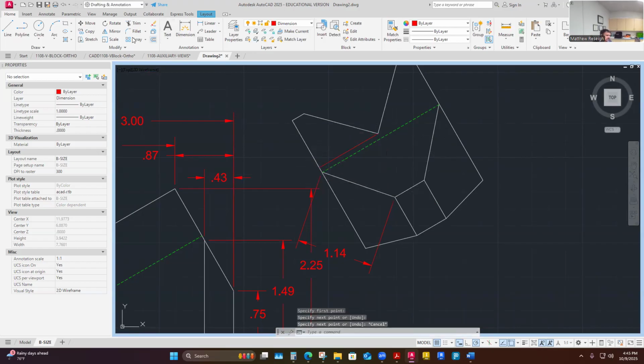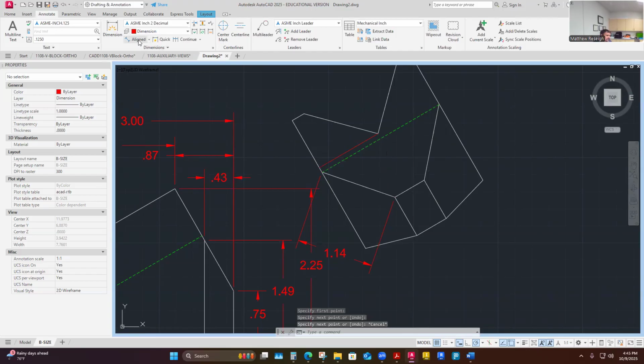So I'm kind of cheating so that I can use this align dimension. This is a dimension I need to have. It's a true length there. It was a dimension that was given to me, and it's the only place it appears in that form to a visible line and not a hidden line. In the front view it would be to a hidden line that I would pull dimension to, so I don't want to do that.